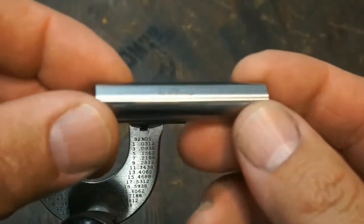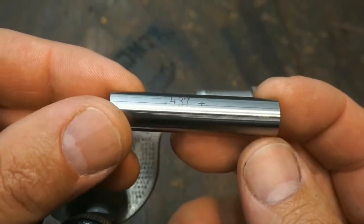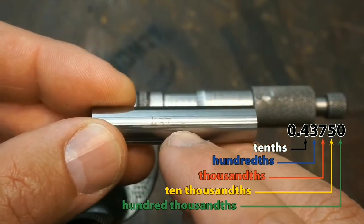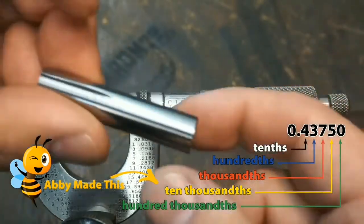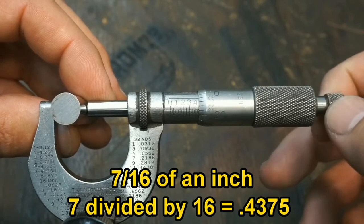All right, so here's one more gauge pin that we'll measure for reference there. This is a 437 thousandths gauge pin. And you see it's got the plus on there, so it is going to measure just slightly over 437. That's going to be in your tenths range. All right, so this would be 7/16 standard inch sizing right there.